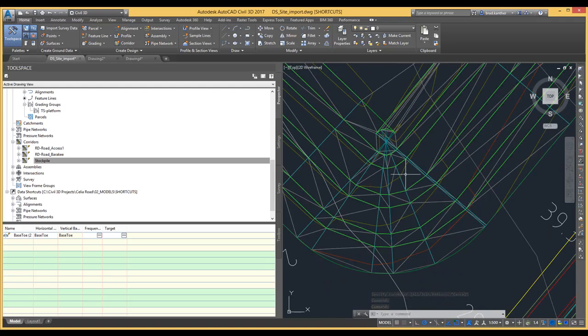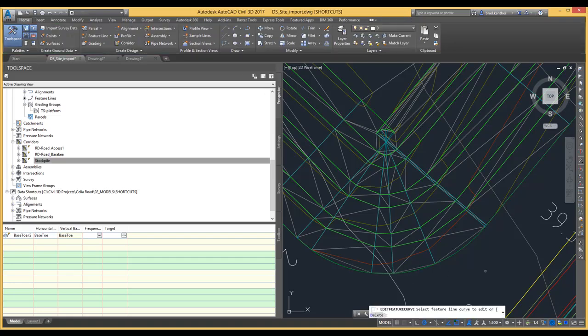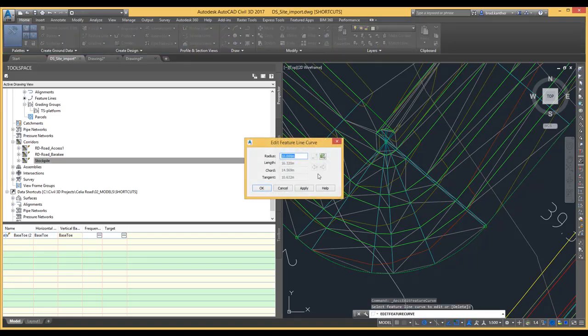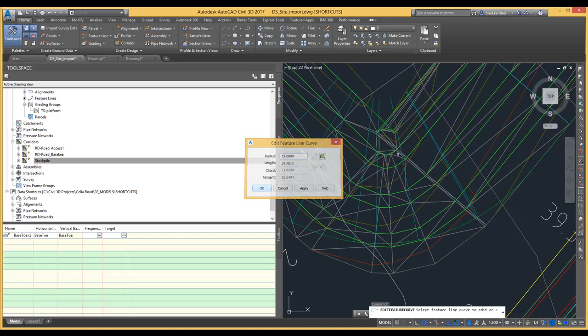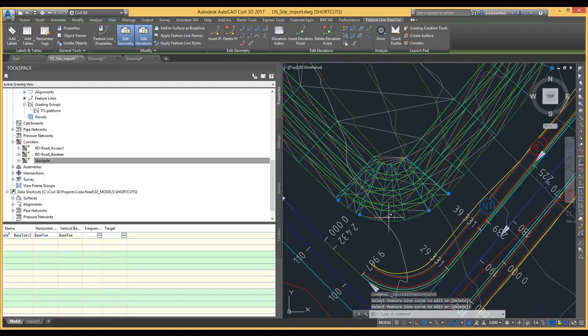The developers at Civil 3D have said, well, if you want a curve, then you should just keep increasing the radius until it no longer is a problem. But I think that's kind of a little bit half-baked, because what if you wanted to have the bottom section as a radius and then the top section to overlap itself? So it doesn't give you much flexibility at all.